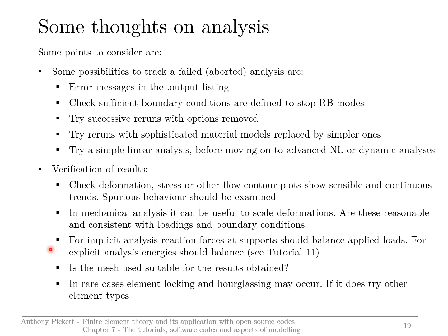Have a look at the results you've got and check that the mesh you're using for the analysis is really suitable for those results. It may be that you've got high stress gradients and yet you've only used a very coarse mesh in some region. You might want to go back and improve the mesh so that this can be better represented.